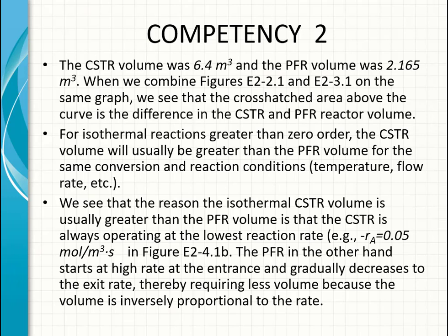The CSTR volume that we obtained was 6.4 cubic meters, and the PFR volume was 2.165 cubic meters. When we combine figures E2.2 and E2.3.1 on the same graph, we see that the crosshatch area above the curve is the difference in the CSTR and PFR reactor volume.